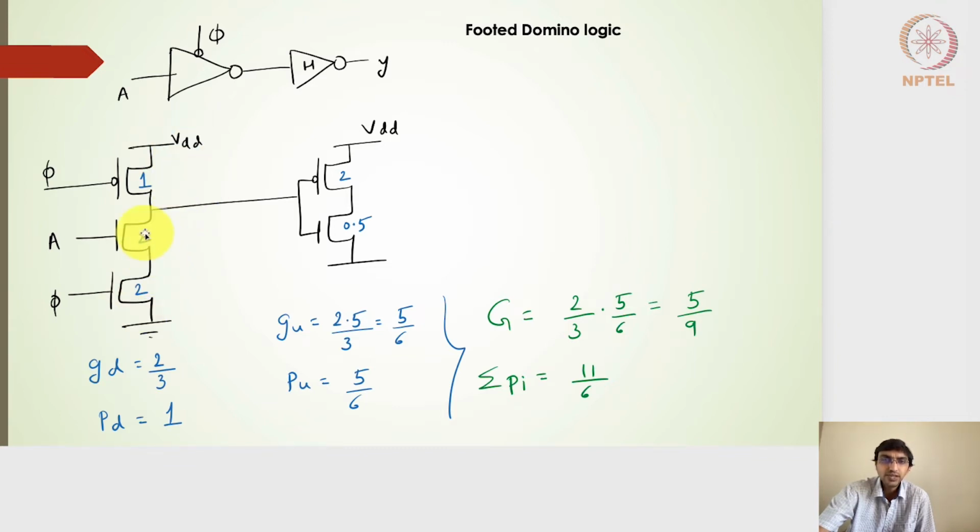The size is 2 and 2, so that the total switching resistance turns out to be R, which is very similar to that of the 2:1 inverter falling resistance. Again, a high skew inverter is applied here in the next stage, so that we will get a really fast rising output in the output of the second stage. So let's try to evaluate the logical efforts.